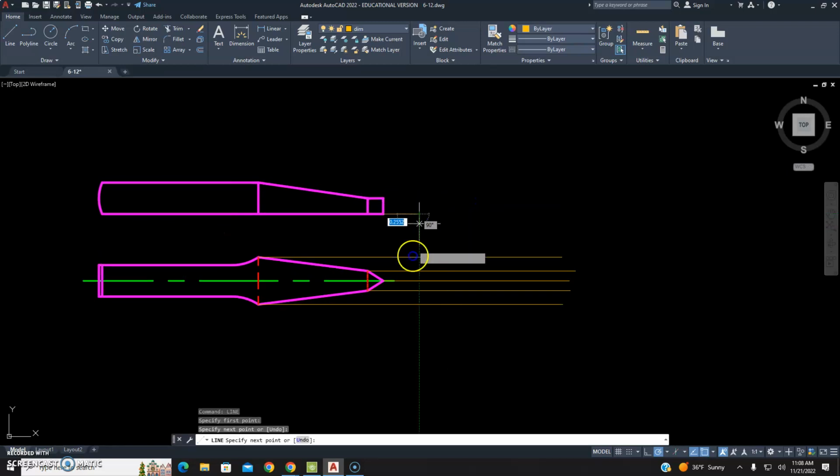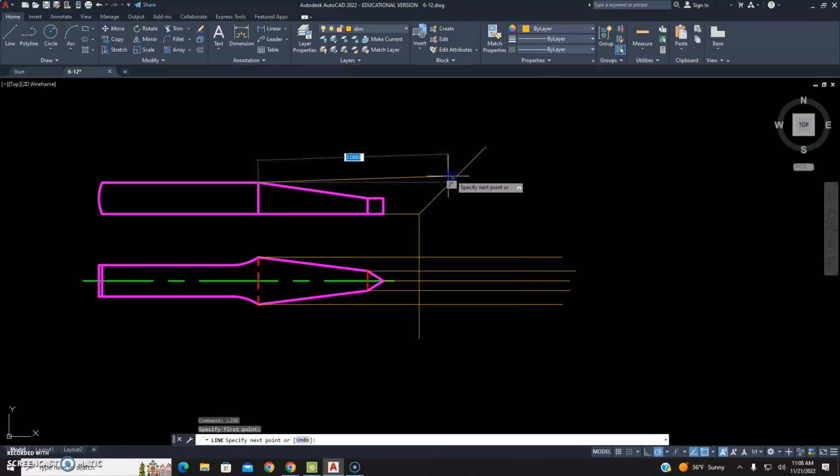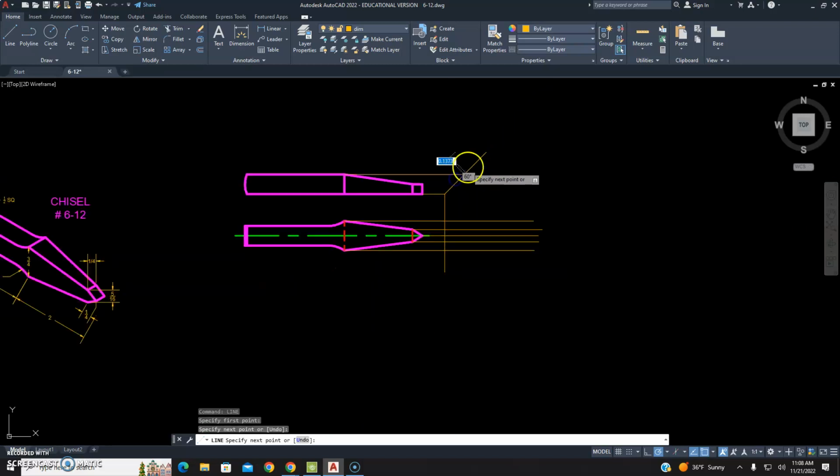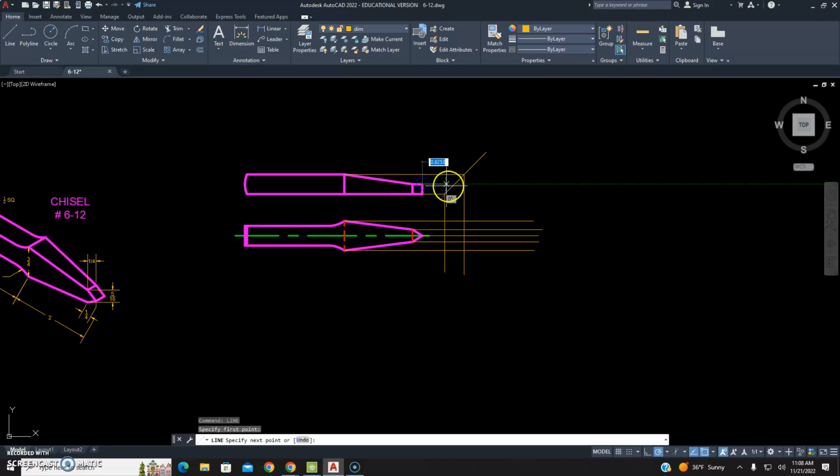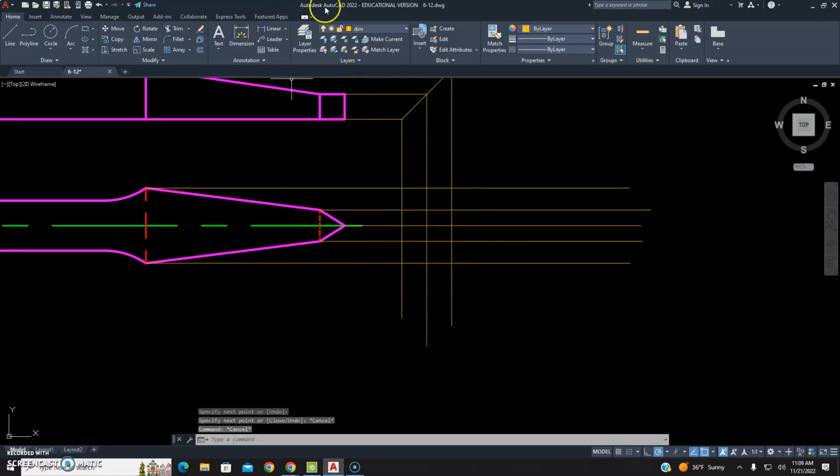And we're just going to draw the bottom over and then randomly draw straight down. We'll draw a line at 45 degrees, and then we'll bring the back side over here and straight down. We'll bring this midpoint here and straight down as well. So our view essentially exists right inside of that rectangle, and what I'm going to do is just draw over top of it with our object lines just to get everything highlighted here.